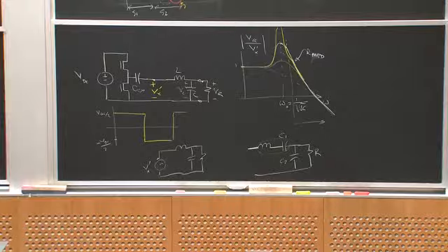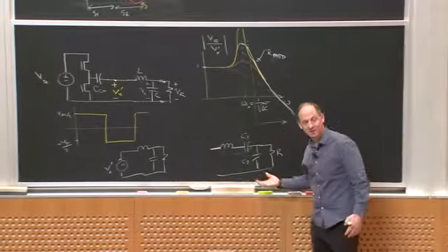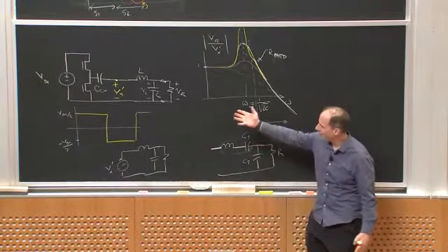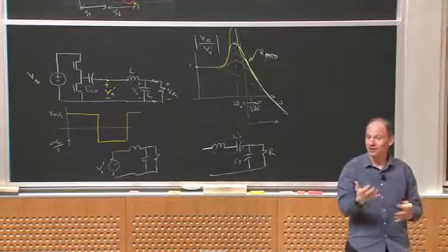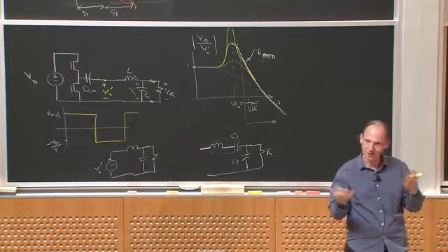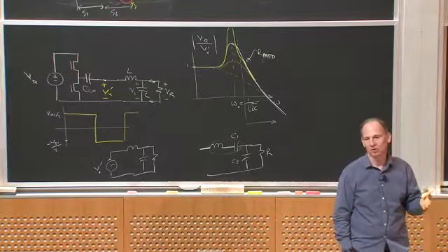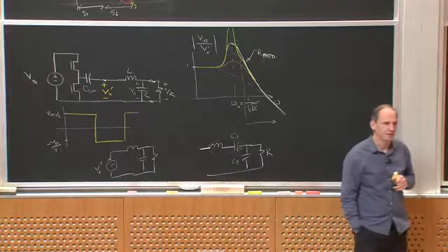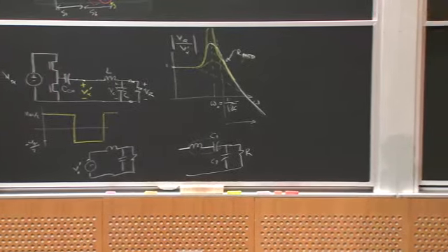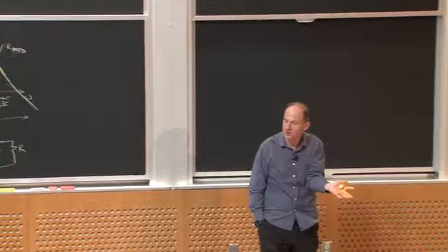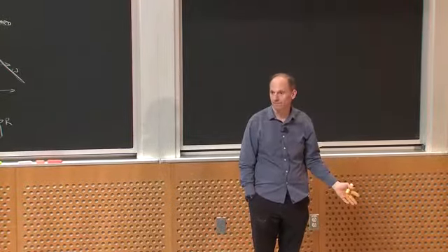And that kind of network's used too to balance what happens at large and small resistances, for example. It has some sort of hybrid combination of series and parallel. You can also have LLC, where there are two inductors and one capacitor. That's another extremely common resonant network. So the easiest thing to get your brain around is the series and parallel kind. There are other kinds that people use because they give particular characteristics for different ranges of load resistance or for different ranges of operating power, for example.